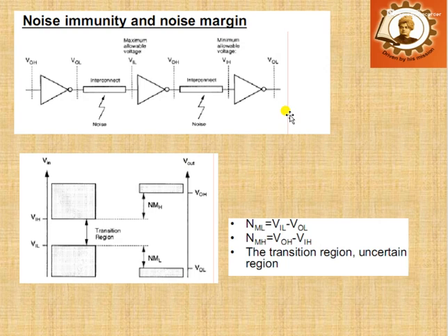So some figure of merit is there, that is called your noise margin. The noise margin is very important while designing some electronic circuit. Noise in an electronic circuit is any unwanted signal, which may be from the power supply or it may be some EM radiation. The noise margin may be defined as the measure of immunity of a logic circuit to perform in a noisy environment.